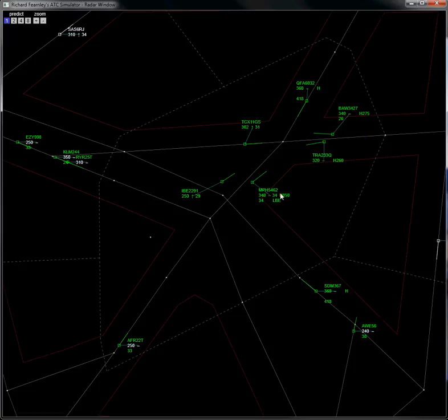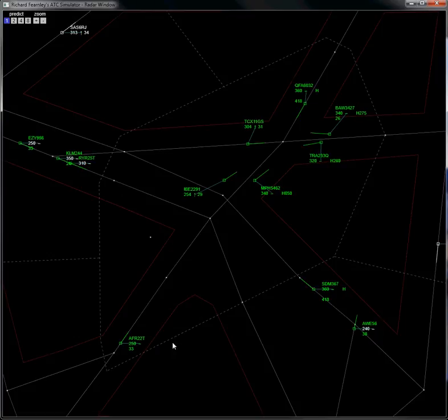And two aircraft are now locked on heading. The Air France 22 Tango has entered my sector. I would assume that aircraft, and I can initially climb it to flight level 290 because of the Ryanair 25 Tango at flight level 310. So I will clear it to flight level 290, and I can reassess that by coming back to it later.